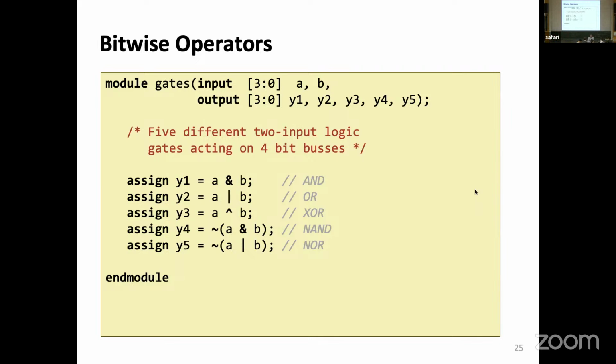So my question is basically, what happens if you have a wire, but both ends are, for example, connected to both outputs? Yeah, that was the issue. Is there a compiler error in Verilog? No, we will not complain about anything. We will just compile it.